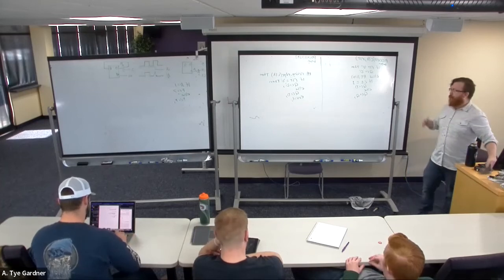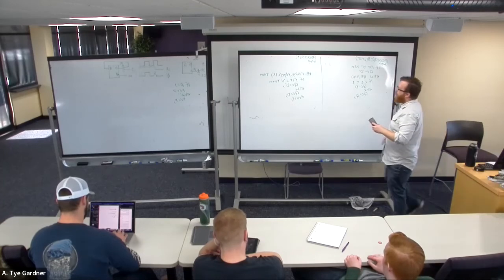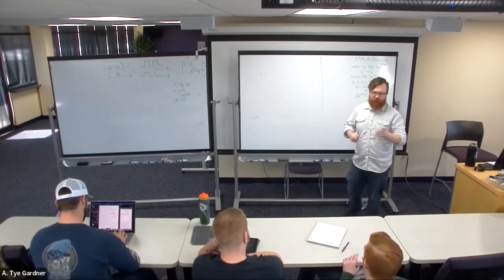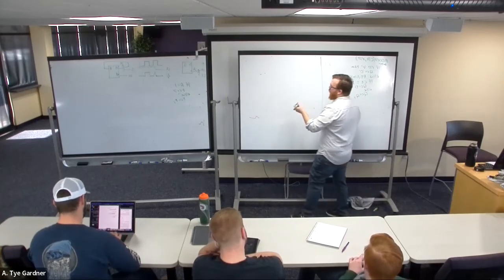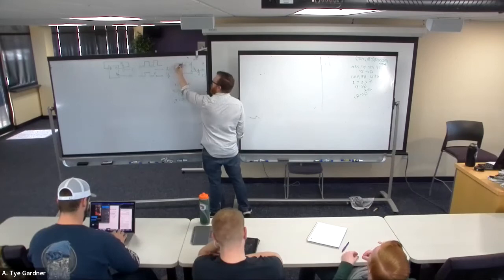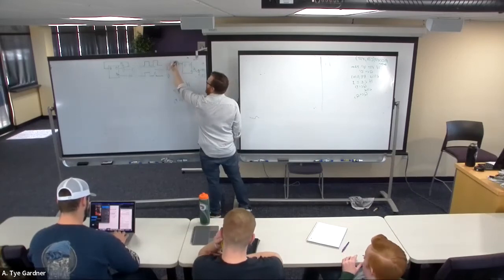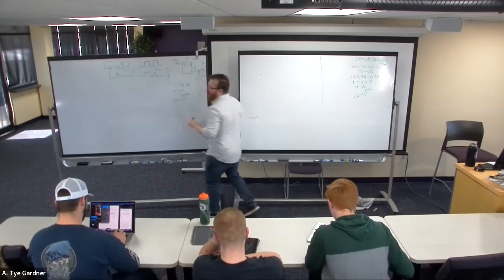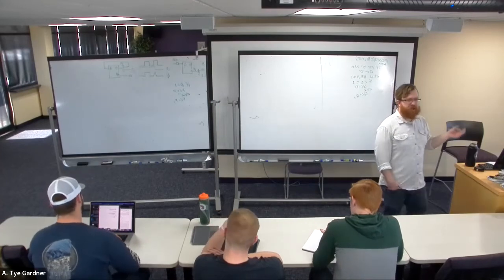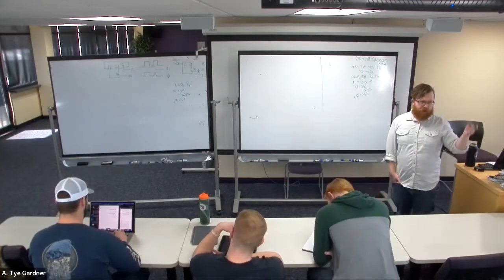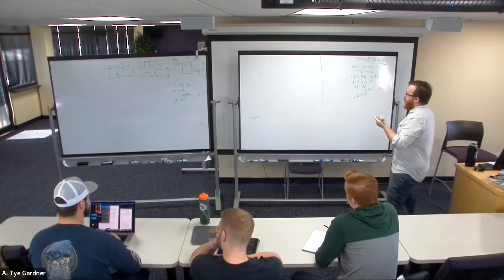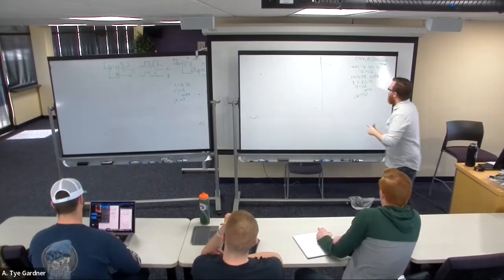Now we can also combine sequential and combinational logic in a design. Makes sense, right? We would want to do both at some point in time. So there's another option where, in addition to a clock enable, I may want an output enable, right? This is just that tri-state buffer that we talked about a couple of weeks ago, which is if output enable is on, the buffer is connected, otherwise it goes to high Z, right? High impedance, it's disconnected.